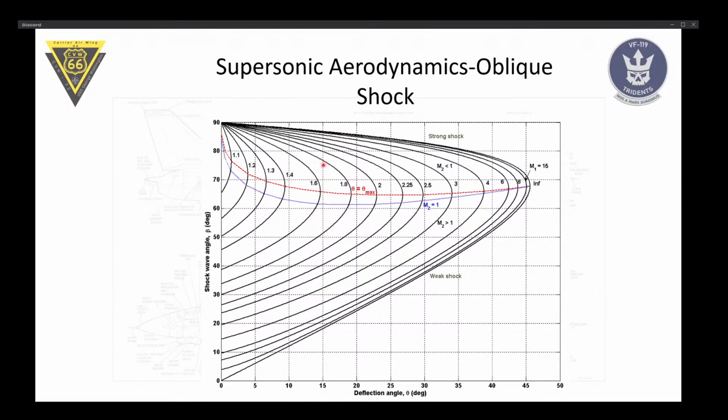The difference is, the upper one is a so-called strong shock. It will decelerate the airflow to below Mach 1, while the lower one is a weak shock, and it's going to decelerate the flow to higher than Mach 1. This is an important thing, as I'm going to show you later, because these weak shocks destroy much less usable energy. So strong shocks are something you want to avoid in your design, because they destroy a lot of energy that you can use, as in the example above.